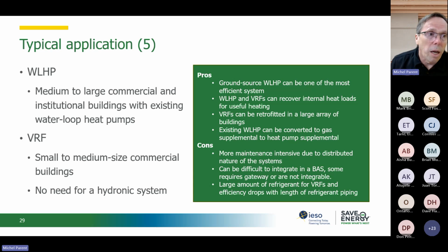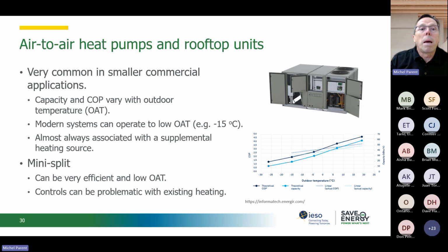The water loop heat pump is a very efficient system. The drawback is the difficulty that you would have in retrofitting that system because of the cost involved if you want to go with extended range heat pump for a ground source system. The easier conversion would be to replace that boiler with an air source heat pump. That would allow you to do quite a bit of decarbonization without doing a major retrofit to your entire loop.